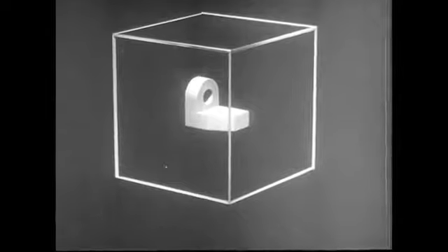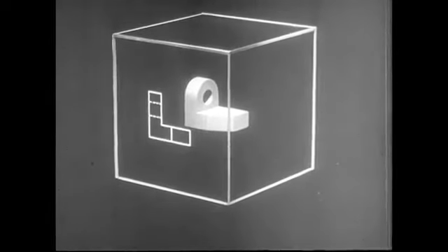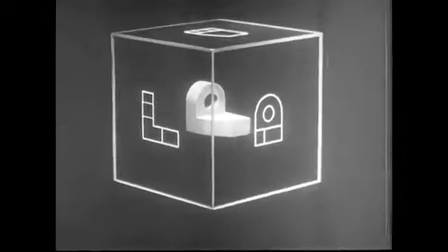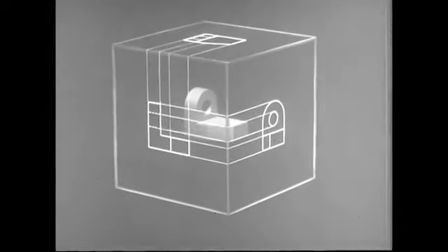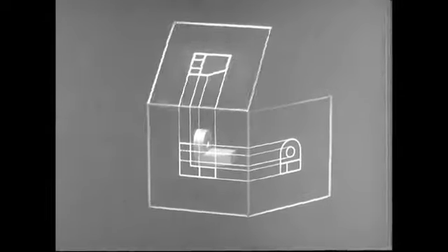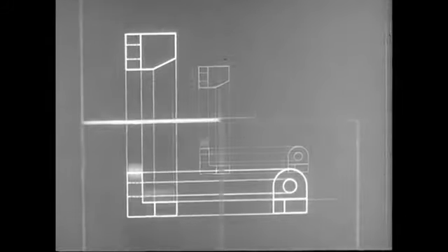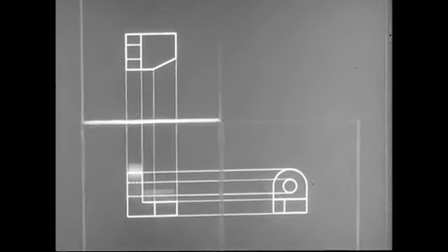You have been able to make this drawing because you know that you need orthographic views, in this case, front, top, and right side views, and that each view must be an exact picture of the object as you see it from that direction. You know also that the projection planes are mutually perpendicular, and that images of the projection lines will become parallel lines connecting the three views when the planes are opened. You know that you must construct your drawing so that the views have this relationship. Then you can project points or dimensions from one view to another, and when a dimension appears in two views, you can transfer it from one to the other.